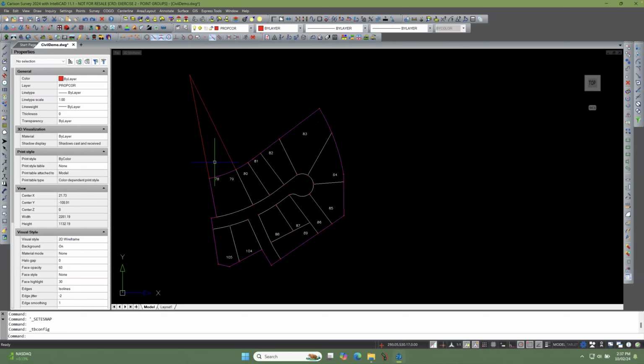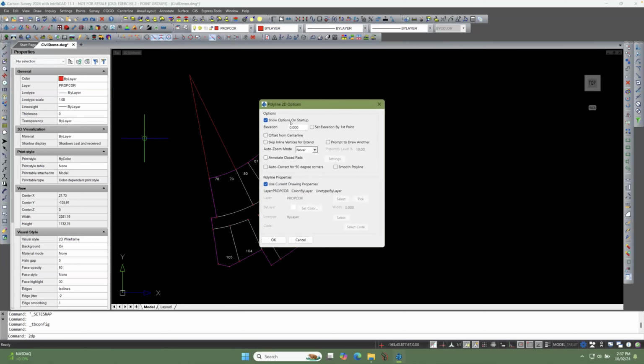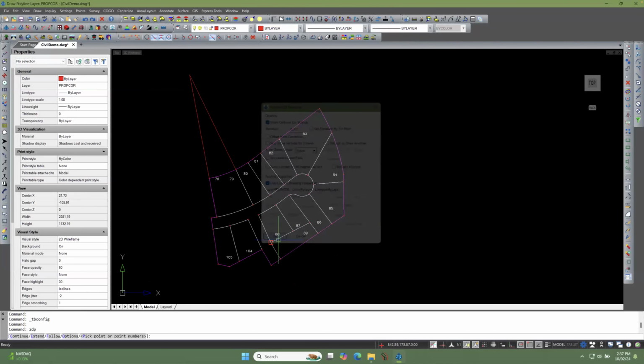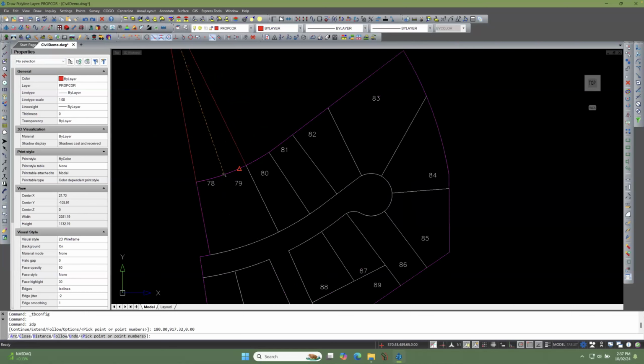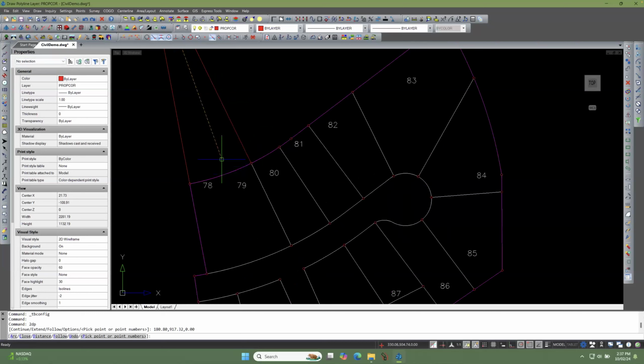And there's a couple of ways. If we draw another 2D line point or 2D polyline, I'll say, okay. Now notice I'm going to hover over here toward the endpoint. So now that's going to be the endpoint. So now where do I want to go up here? I can't go to the midpoint. See, that's the midpoint of the arc.